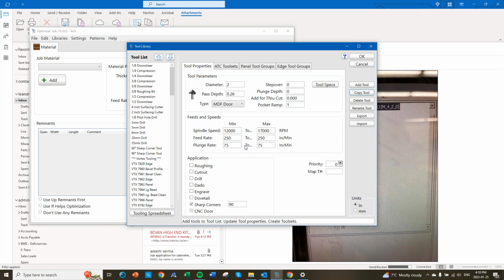We have now in Mosaic, we don't need to put in a flat cutter because all we're talking about here is what we're going to use to cut cabinet parts. Flat cutter is never used for cutting cabinet parts, so we don't have to include that in here. On your machine for surfacing a spoil board, that's fine, but we just don't need to tell Mosaic about it. I can use the program that's already set in there.